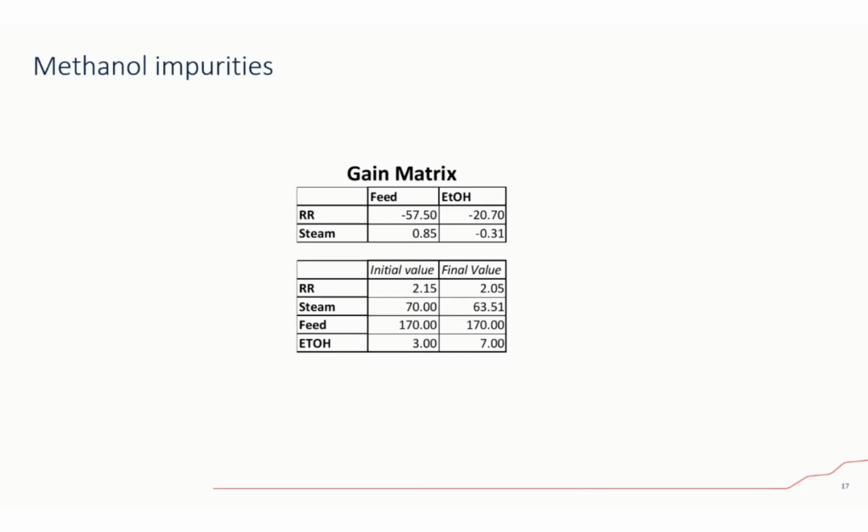Whereas in the case of just simple PID cascades, they will always be acting on feedback. So if you configure a bunch of cascades to try and achieve the same result, you will have to make one of those cascades, or several of them, slower than the others, because only one of them can quickly react on feedback, and the other ones just need to slowly react on feedback to accommodate for what the first one is doing. If all of them are acting as quickly as they can, they will just exacerbate the interactions and most likely lead to an unstable situation.